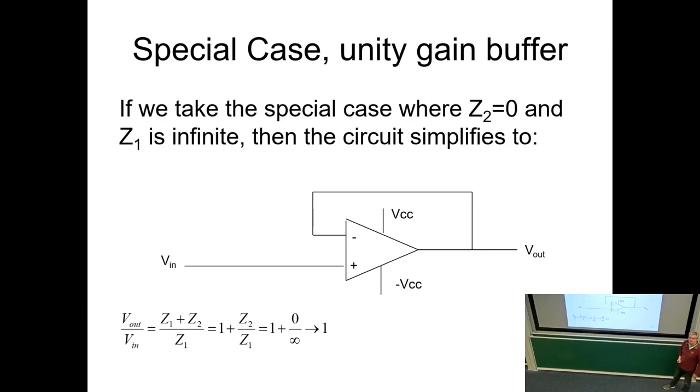So it's a really useful circuit when you've got something really complicated that might not be behaving quite as you think because loading effects, which vary with frequency, remember, are causing all kinds of grief. Separate your circuits with one of these, chances are the problem will go away. This is a really, really useful circuit.